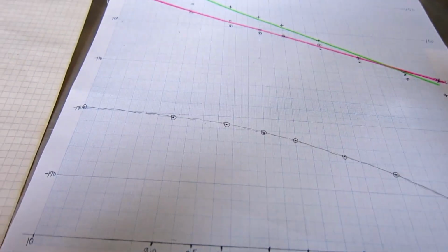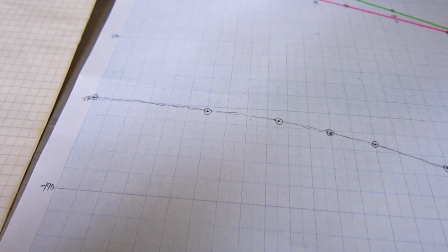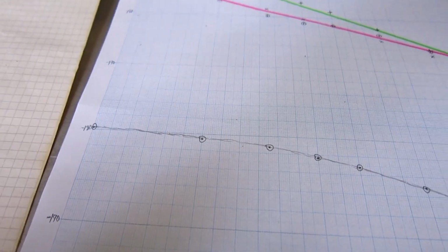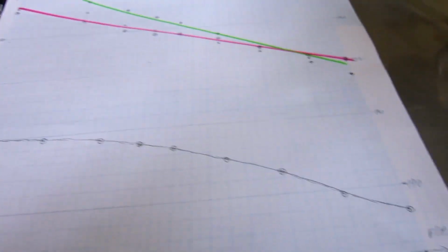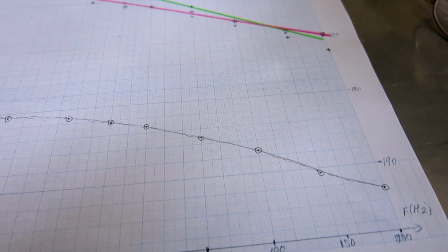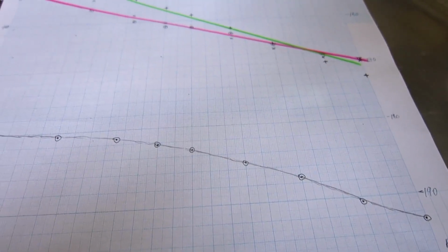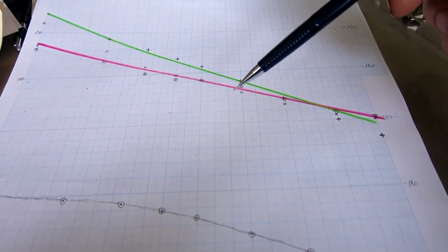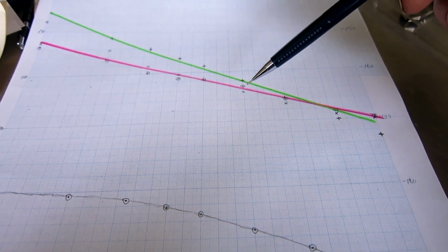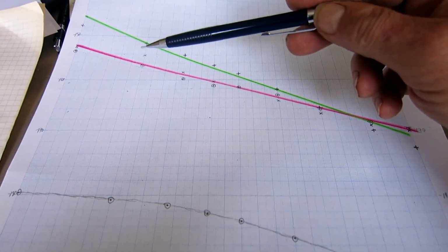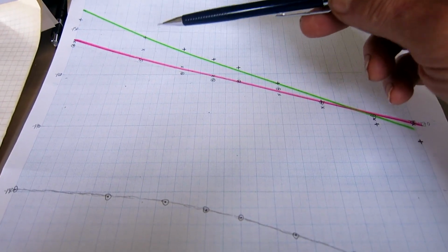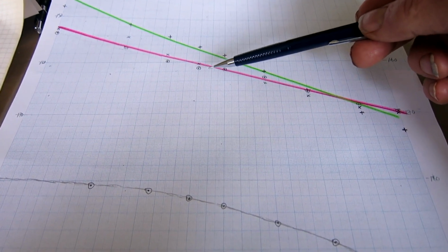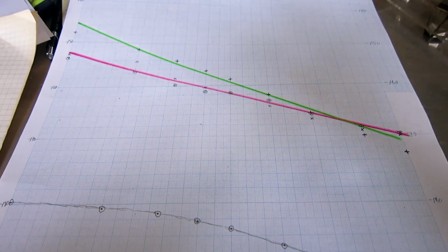So I add the minus 60 decibels attenuation and plot the thermal noise of the crystals plus the amplifier noise on the same diagram. And it's clear the contribution from that is of no concern at this signal level. The sideband noise from the crystals is the dominating problem, and there is also a little flicker noise on the amplitude from the amplifier. But the crystals determine the performance up to the output of the first amplifier stage.